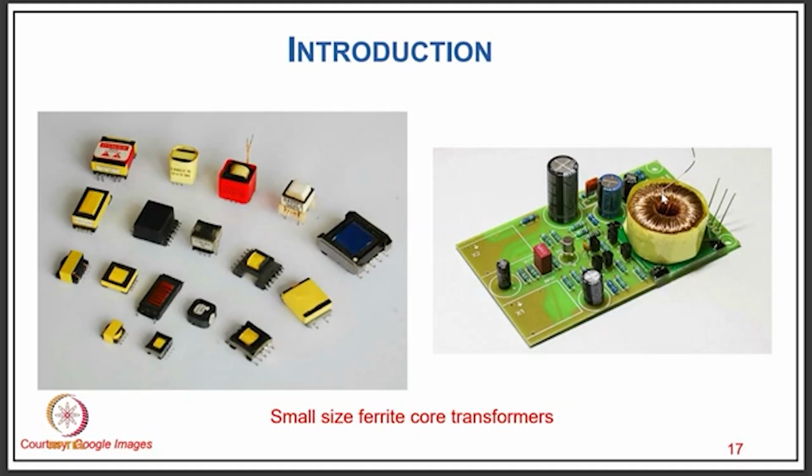I mean, new applications also emerge, like welding and others, even for many electronics equipment, as well as typically in the case of power electronics applications for the purpose of isolation for gate drive and other applications. So there we are using this high frequency transformer for many purposes. One is isolation, and another is to get many output voltages so that we can convert into many DC